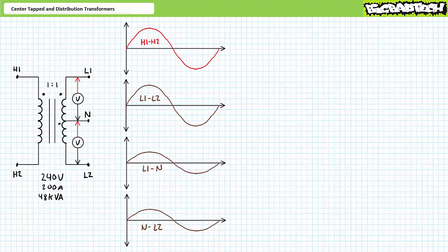Again, given this system is presently floating with no reference to ground, this would result in three possible outputs: L1 to L2 with 240 volt differential, L1 to N at 120 volts, and N to L2 at 120 volts, all in phase with one another. This should be a review of the contents we previously discussed in the transformer connection diagrams lecture. Let us now consider these two subtle modifications to this system.